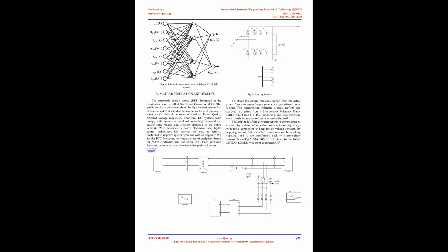It is important to note that the instantaneous reactive power, q(t), means more than just the usual reactive power. The instantaneous reactive power takes into account all the harmonics of current and voltage, whereas the usual reactive power considers only the fundamentals of current and voltage. From equations 3.4 and 3.5, the active and reactive instantaneous power can be given in the form of a matrix, 3.6.